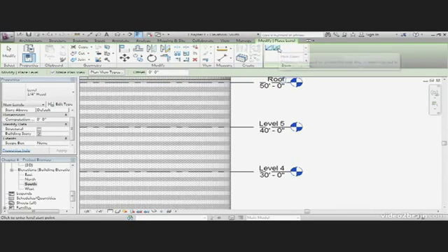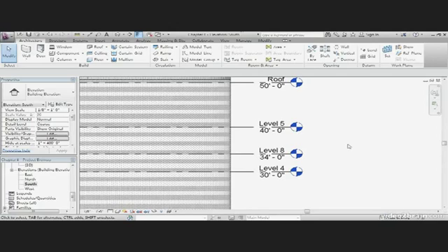On the drop panel, click the Pick Lines button. On the options bar, let's get an offset of 4 feet. Let's offset level 4 up 4 feet. And let's hit Escape. It calls it level 8 just because it doesn't know what else to call it. Obviously, we know we can rename it.